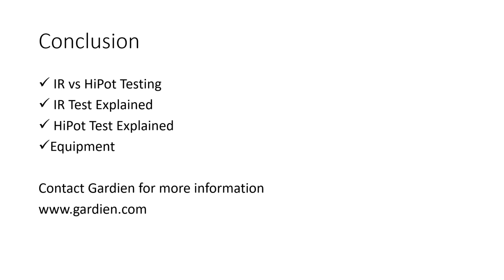And then wrapping up there, we talked about our options and solutions for your needs, whether it be flying probe equipment for your site or sending your product into us to get those tests done, which we can do either on flying probe equipment, or we can develop the switching type fixture, which we can test arrays and multiple pairs on bigger boards, which, by the way, we can do that as well on the probers. But with the switching fixture, it does give us a little bit better idea of how to isolate a fault if it does show up during the test.